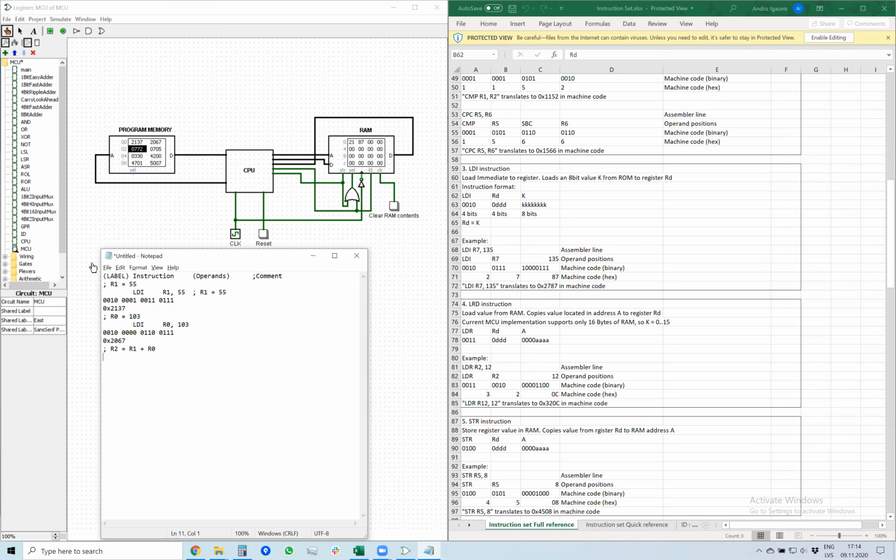And the first of them is, for example, copy register R1 into R2. Copy one number into the result and then add the second number into the result. So the first thing that we need to do is copy register R1 into R2. Copying a value from one register to another in most assembly languages is called mov, from move. In some other assembly languages, I think in Texas Instruments, it's called copy, CPY, but I think that in ARM and in most other languages it's called mov.